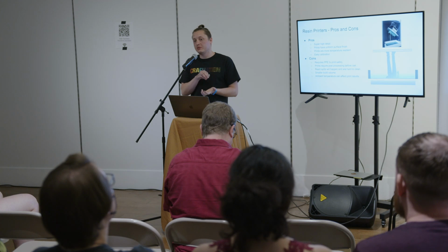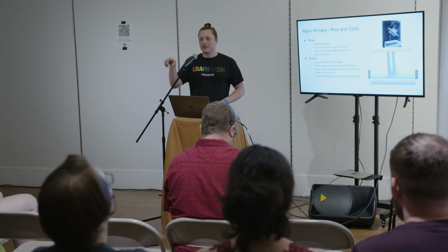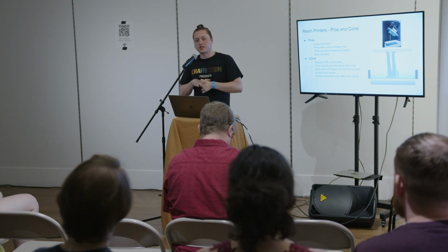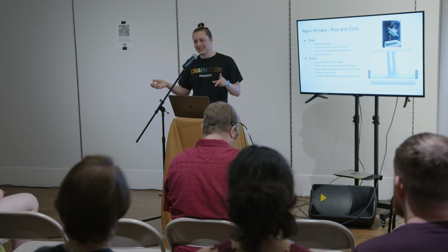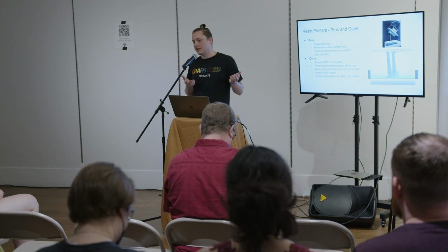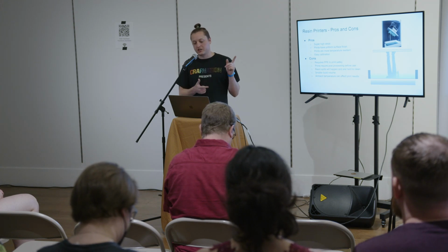Yeah, the prints tend to be much more temperature resilient. PLA's glass transition temperature is like 60 degrees Celsius, which I don't know what that is in Fahrenheit. But if it sits in a hot car, it can deform. So it's low enough that potentially everyday things might cause it to deform. Resin prints tend to be much more temperature resilient. I've actually used them as molds for injection molding, which is like 240 C or above, and it holds up reasonably well.